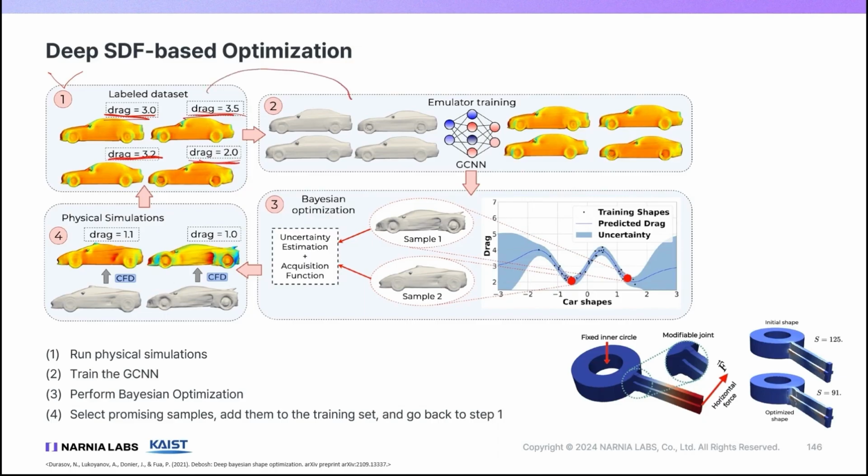After that, since we've generated X and collected Y data here, we can use deep learning to train the function y = f(x). After training, we use that as the basis for optimal design. Once we've performed optimal design and found a good design, we run an actual simulation on that design again to verify the results. So the good values are fed back into the data set, and then we generate new data using that data set again. We retrain on the new y values, and this process is repeated iteratively.